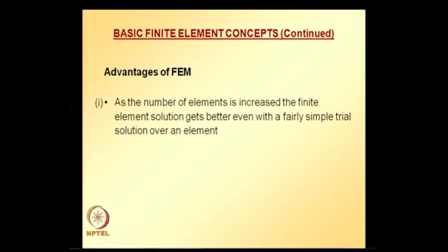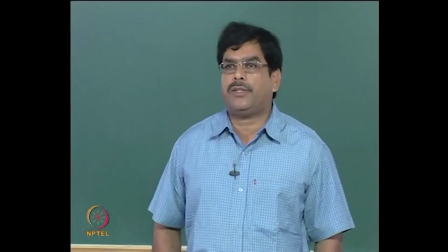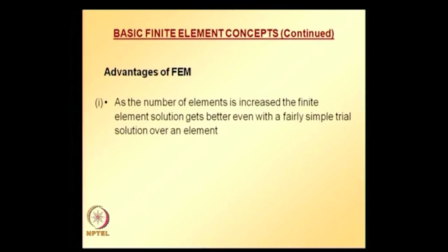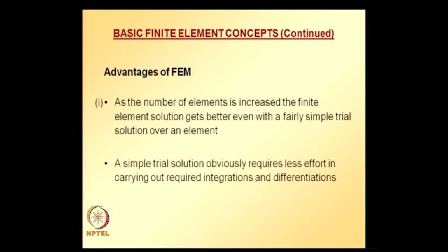Based on the observations that we obtained with this experience, the advantages of finite element are, as the number of elements is increased, the finite element solution gets better even with a fairly simple trial solution over an element. Please remember that we have used the simplest trial solution that we can use, that is linear trial solution, and as the number of elements is increased, the finite element solution is getting better. A simple trial solution obviously requires less effort in carrying out the required integrations and differentiations.